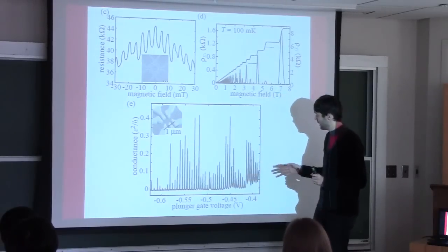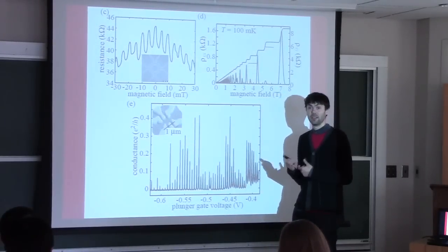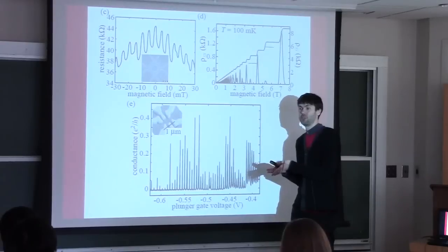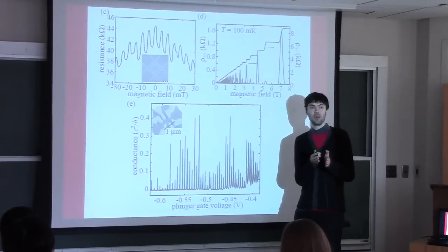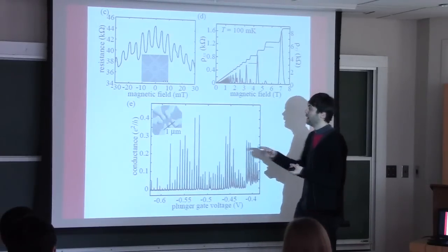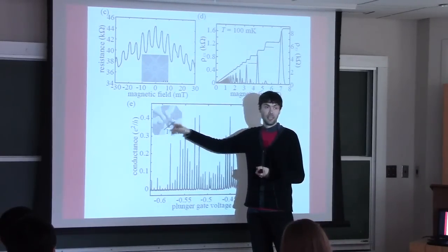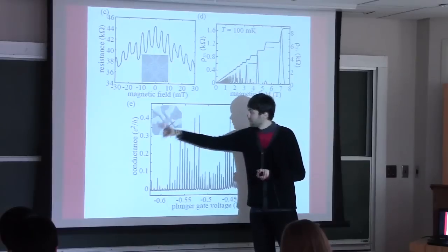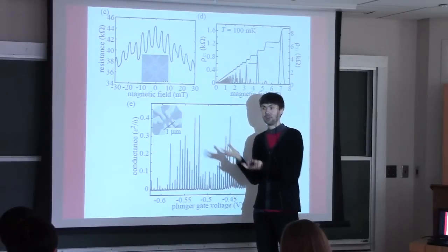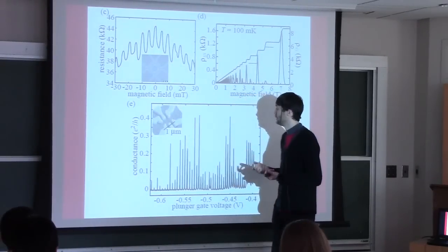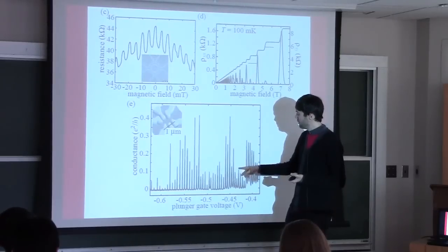So that means that at each peak it costs you equal energy to have n electrons and n+1 electrons on this island. And therefore, you can freely add electrons and they will come out. And that means you can have transport. Yeah, so certain energies are equalized. And that gives you a peak in conductance.